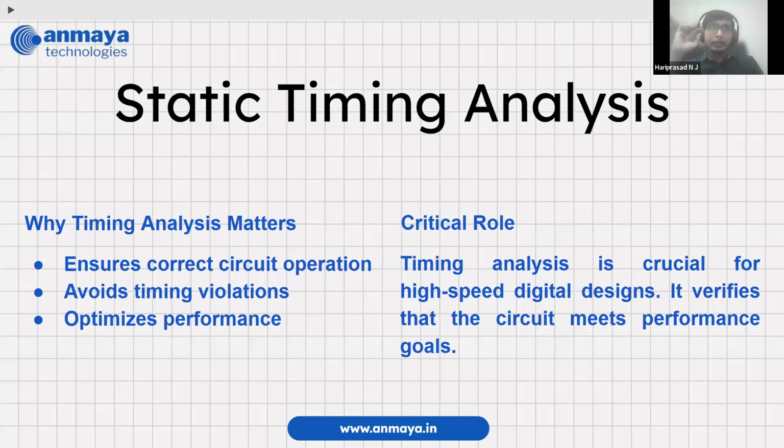In terms of performance also, we have to optimize. Whenever I have a setup violation, the general way I can solve it is to reduce the clock speed. But reducing the clock is not a solution. Let's say my clock is operating at 100 megahertz and you see the setup violation.